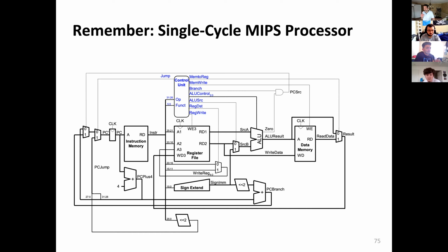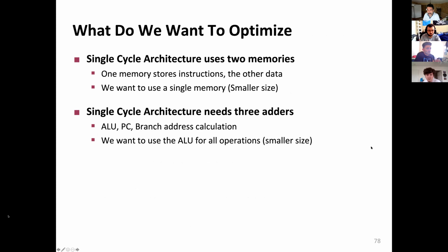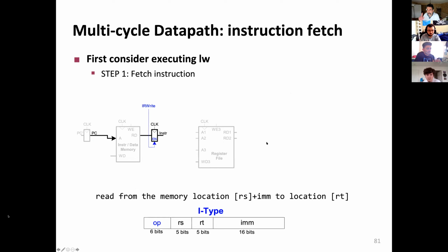In multi-cycle, listen very clearly, we could not get away with that. Why? It's simple. If we write to this register file, imagine that I'm removing this and writing to the register file, think, each step, each state is one cycle. When the clock has finished and we go to the next clock cycle, the programmer will see that the register file has changed. And this property has been violated because the register file is part of the architecture state.